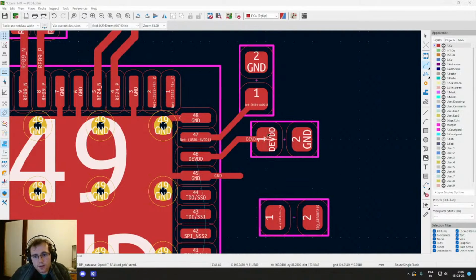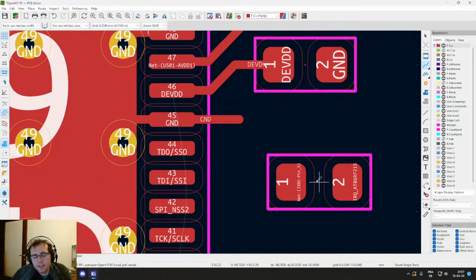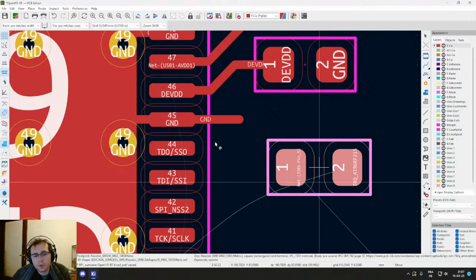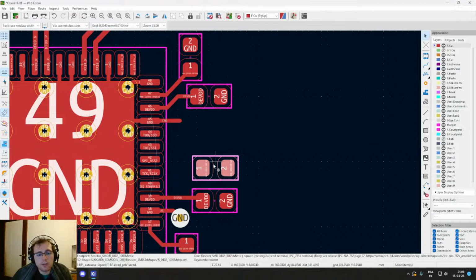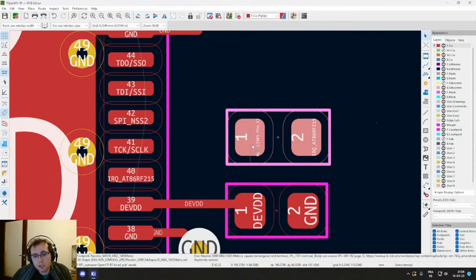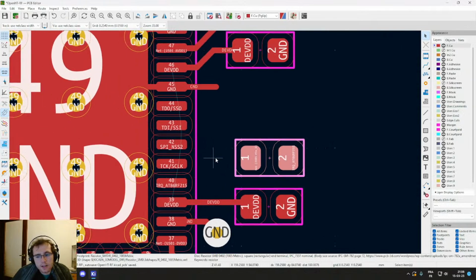Yeah, so can you see, actually the dimensioning of the footprint is related to the IPC standards, which is a big group that determines how you should design a footprint with regards to the density of the boards, the size of the components, the type of components, the quantity of solder and the heel that you want on the solder joint and so on. Lots of things that you usually don't do by hand, so you have calculators and scripts. KiCad relies on a script that is in another repository on GitLab, that you can find if you look for it, and it will generate the footprint.